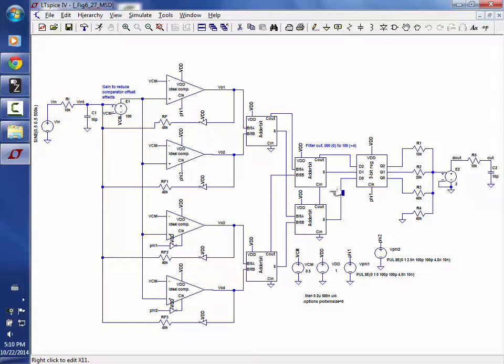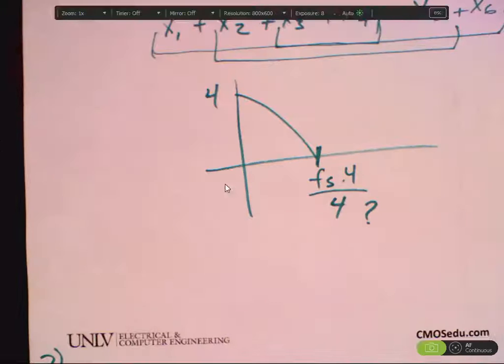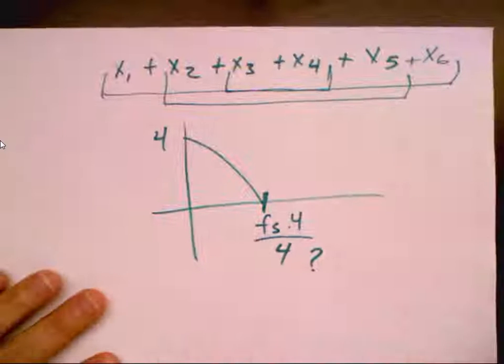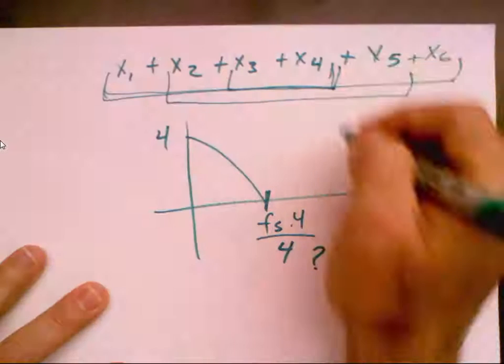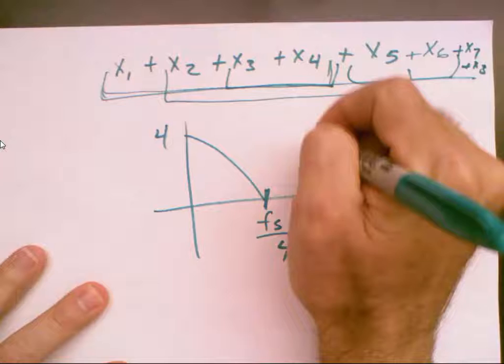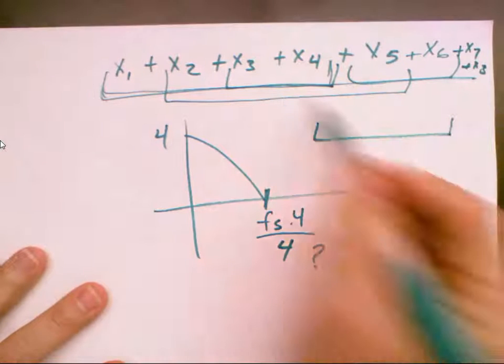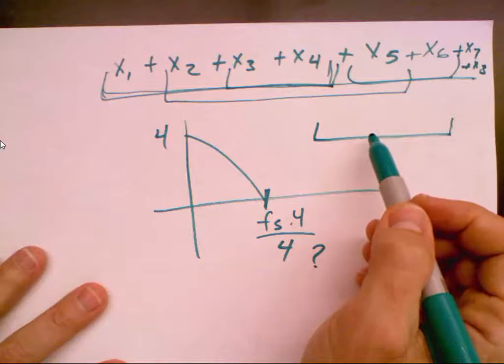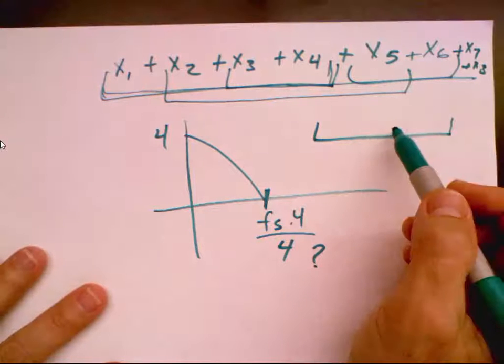You're still storing all the samples, so it's exactly the same. Sample 1, sample 2, sample 3, sample 4, clock in. Sample 1, sample 2, sample 3, sample 4, clock in. So I'm going to sum 4, then sum the next 4, then the next 4, clocking it into the register, so the output that goes into the DAC will change at 100 megahertz.